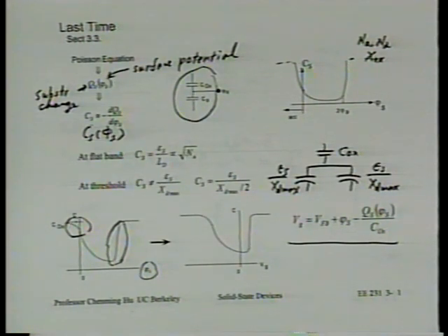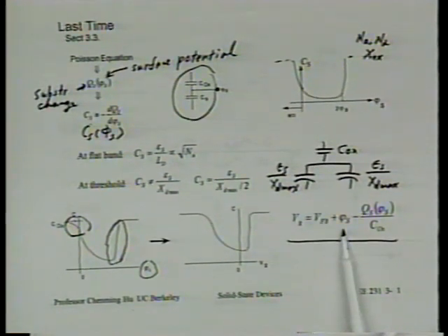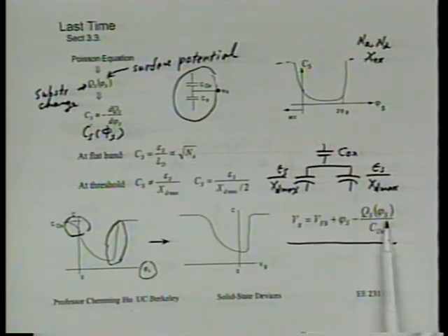Vg is equal to VFB plus phi s minus Qs over Cox. Remember that equation? That says Vg equals VFB plus the substrate voltage plus the oxide voltage. Is that right? Now, why does this relate Vg to phi s? Well, certainly the phi s term is phi s. But this Qs term is also a known function of phi s. Is that right? It's a complex, difficult function, but it's a function. So for every point on the phi s axis, we can write down a corresponding Vg value. That's how we end up with CV characteristics. Is it okay?